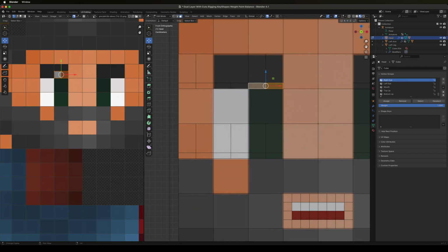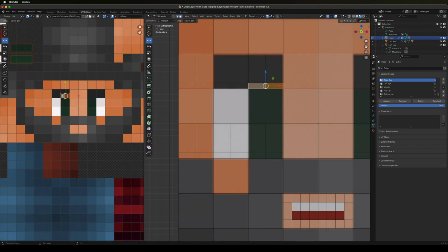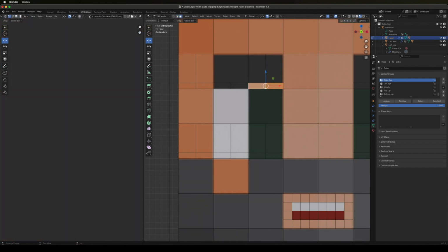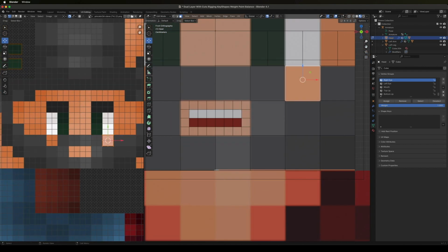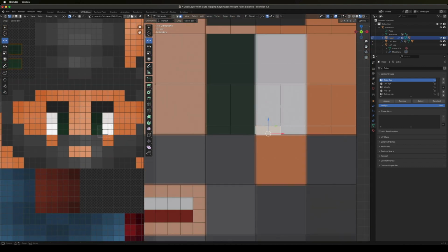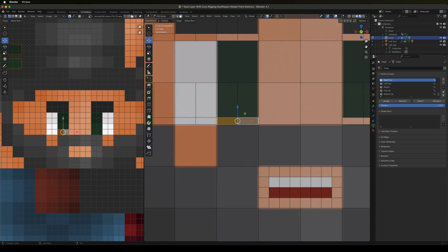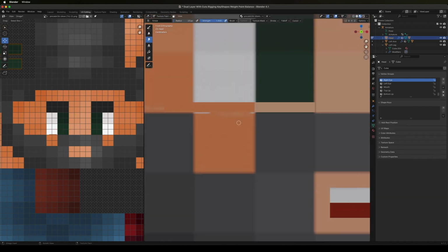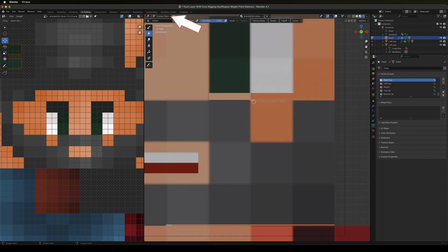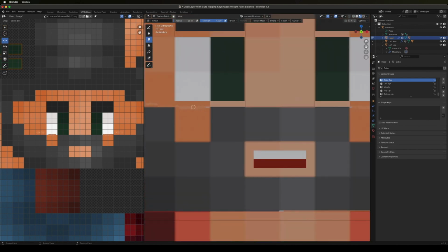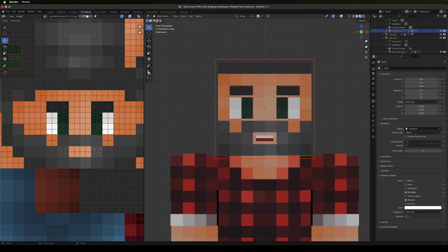With the subdivided zones at the top and bottom of the eyes, we'll move the midpoint of these subdivided zones and set the texture maps of these new skinny zones to nearby facial tones, so that we get an actual gap above and below the eyes. For textured regions that don't quite blend in neatly, we'll use the texture paint mode and blend those regions to make it neater. The face now looks reasonable, with a distinct mouth, eyes, and eyebrows.